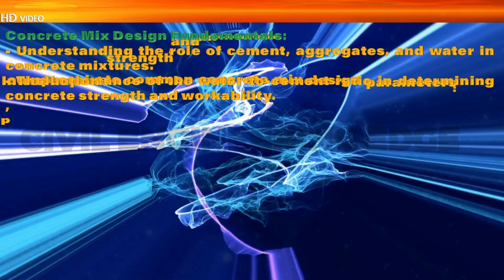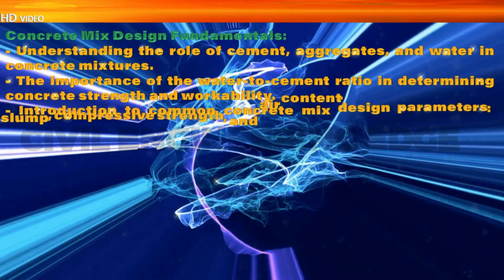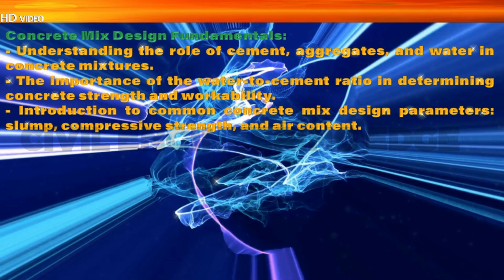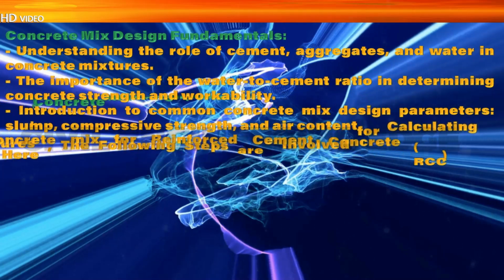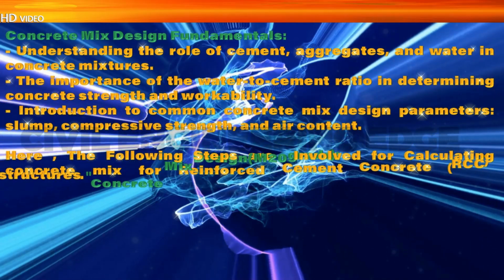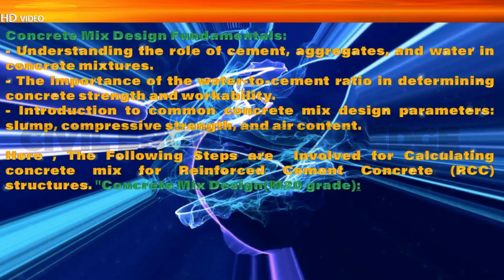Here, the following steps are involved for calculating concrete mix for reinforced cement concrete, RCC structures. Concrete mix design, M20 grade. 1. Target strength. 2. Water-cement ratio. 3. Water content. 4. Calculation of cement content. 5. Aggregate proportion between coarse aggregate and fine aggregate. 6. Mix calculation.